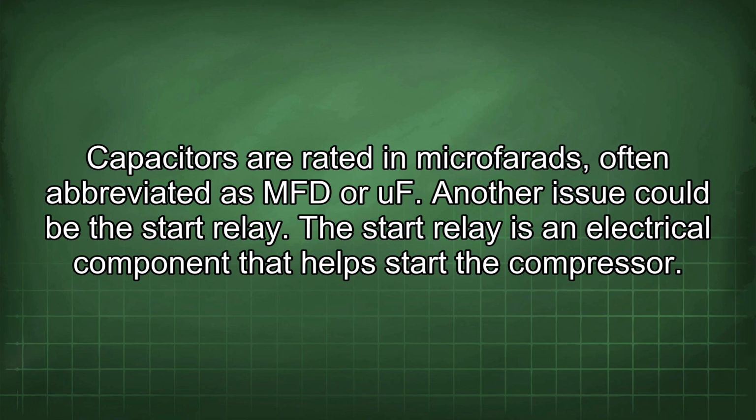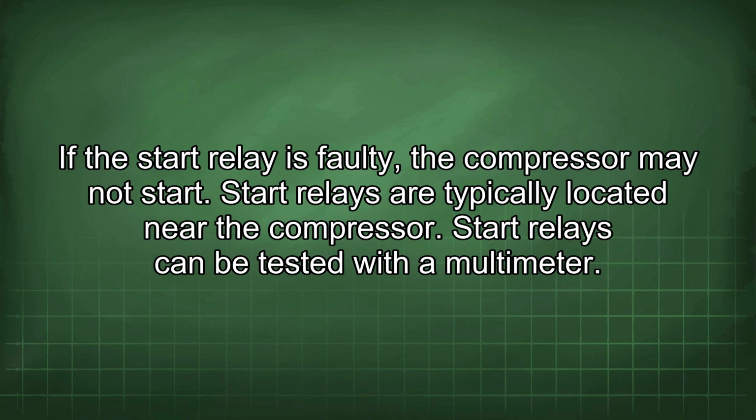Capacitors are rated in microfarads, often abbreviated as MFD or UF. Another issue could be the start relay. The start relay is an electrical component that helps start the compressor. If the start relay is faulty, the compressor may not start. Start relays are typically located near the compressor.